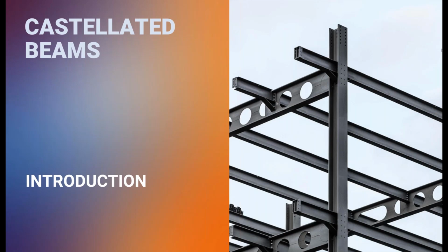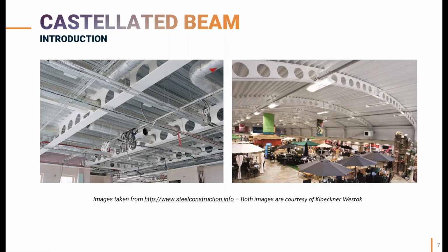Good. So I would also like to welcome our attendees, and without further delay, move to this webinar where we will discuss beams with web openings. As an introduction, beams with web openings, also known as castellated beams or cellular beams, have become a very common requirement in construction projects because they have a very big advantage. They allow the incorporation of services into the structural height of the beam, and they can essentially hide the services into the ceiling, which leaves clean space that the architects love so much.